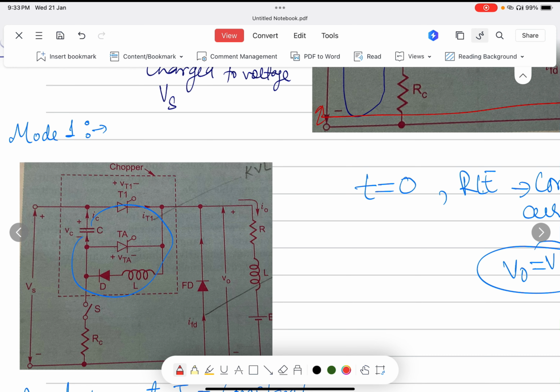The first method is that if we just switch on, the supply voltage starts flowing through the capacitor and has a return path through the resistor to the back path. So the capacitor will get charged. When the capacitor is charged to the supply voltage, the charging current is equal to 0. I have already discussed that in various classes. So this capacitor gets charged.